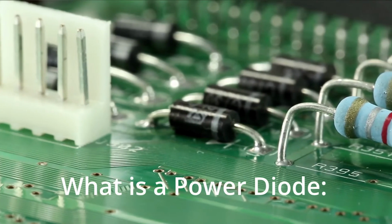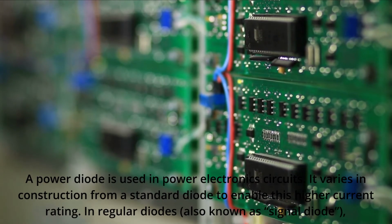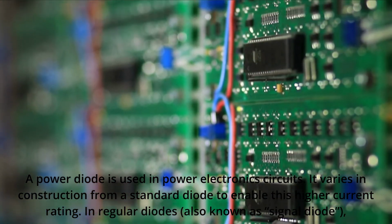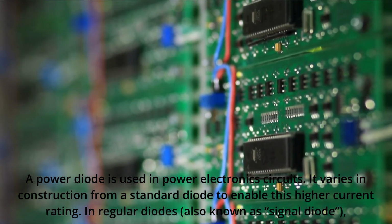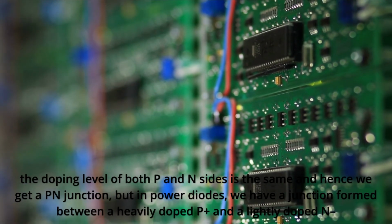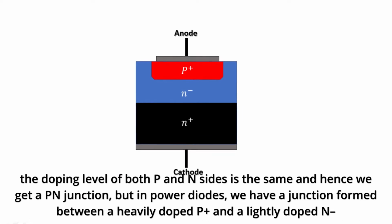What is a power diode? A power diode is used in power electronics circuits. It varies in construction from a standard diode to enable this higher current rating. In regular diodes, also known as signal diodes, the doping level of both P and N sides is the same, and hence we get a P-N junction.